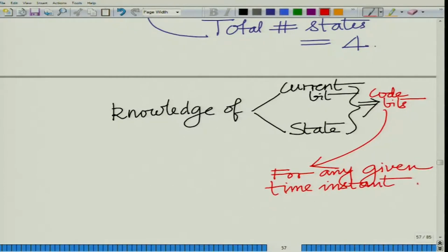So as to say, this convolutional code has a memory, because you need not only xj but xj minus 1 and xj minus 2, and this memory is captured by the state. Memory represents an evolution of the system, and that evolution is basically captured by the state. And now the convolutional code can be represented using a state transition diagram, which shows the various states.